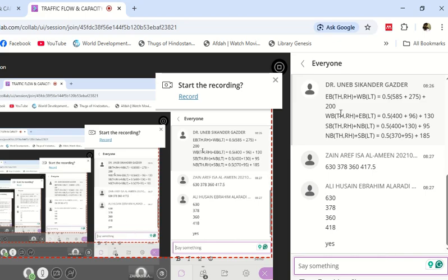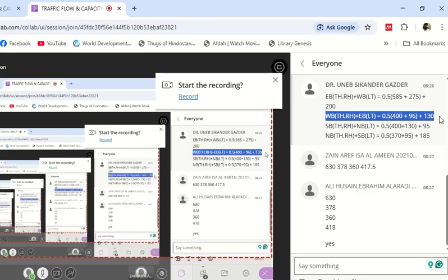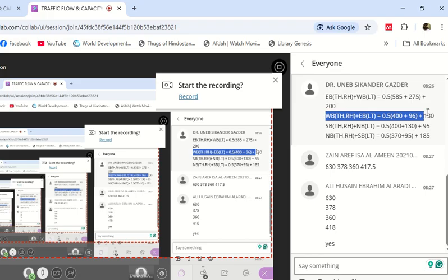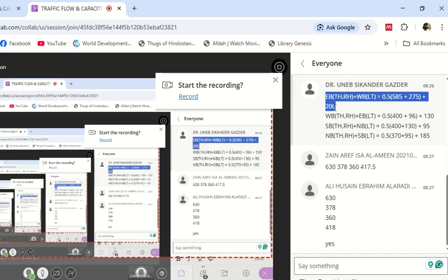Okay, so now either this can happen or this can happen. This will happen in one phase, or this will be one combination of phase, and this will be the other combination of phase. Either you can allow, in one phase, westbound through, and the conflicting phase, the other phase, will have eastbound left, because they are conflicting, right? So they cannot be in the same phase. So one conflicting pair is this one, and the other conflicting pair is this one.